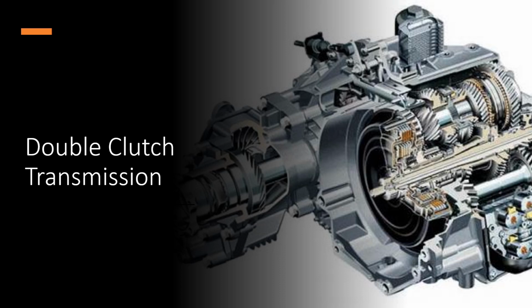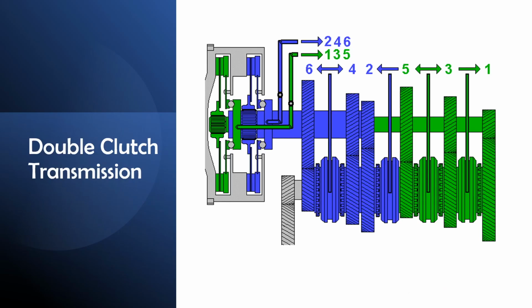Many people confuse this transmission with an automatic one, but it's only semi-automatic. Actually, it works like a manual one, but only has 2 clutches, 2 input shafts and 1 output shaft. The gear changes are done by a mechatronic module. Here you can see the 2 clutches, 2 input shafts, 1 full shaft and 1 around, this one also named hollow shaft. One shaft takes over the even gears and the other the uneven gears. Reverse gear can be on both shafts.